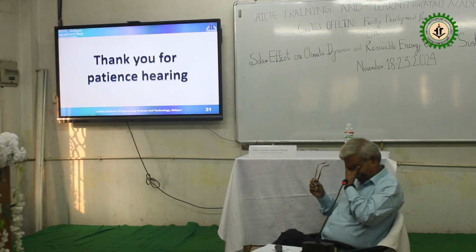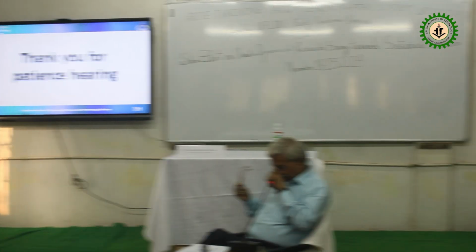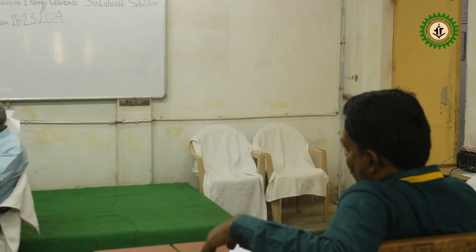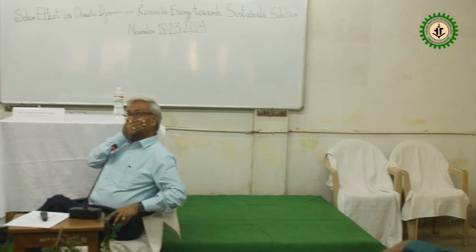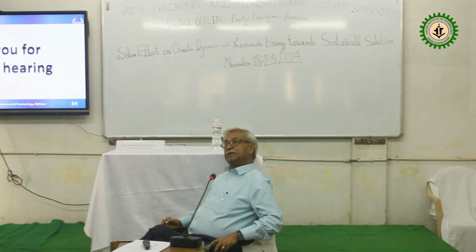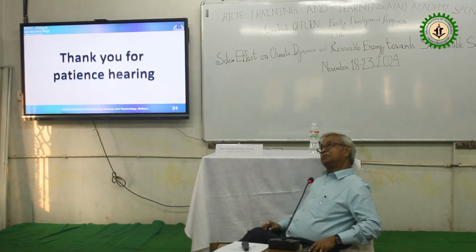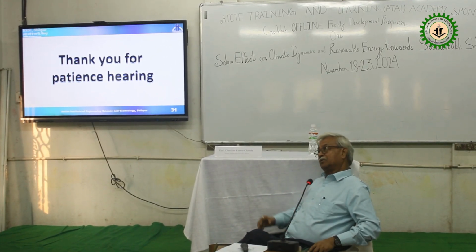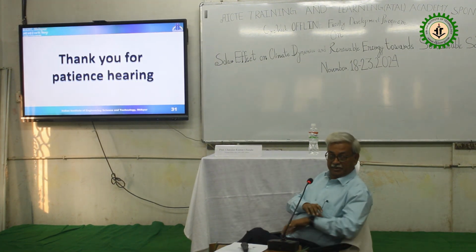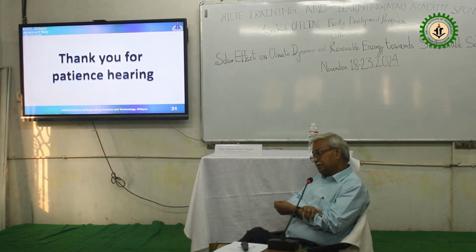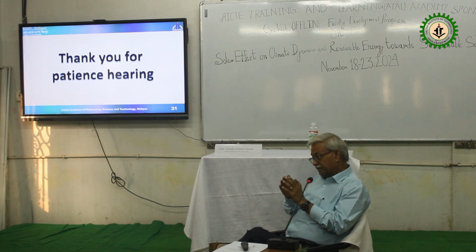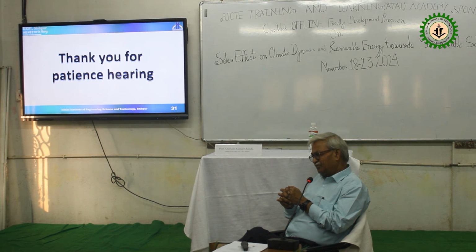So it is kind of organic inertia or synthetic inertia when it is coming from the generator, the synchronous generator. A synchronous motor is already there in the system, so you are not adding to that. Synchronous condenser, if you adopt it in the system, can be considered as a virtual inertia. It is not formally considered so, but technically speaking, it is a kind of virtual inertia to me.